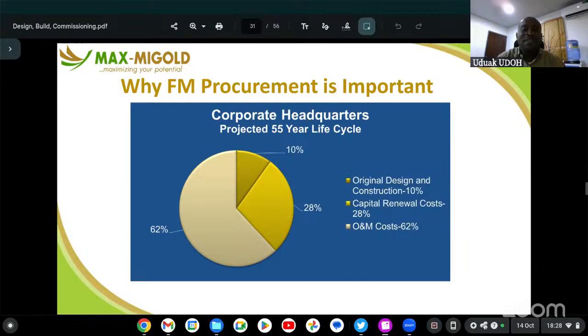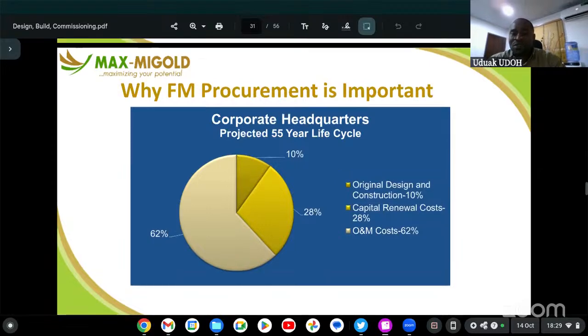And whether spares are available, because there are some things you get and there are no spares, so what will you do? If I'm getting a particular asset and purchasing it for like 20,000, for instance, and then weekly I'm maintaining that asset for 5,000, does it make sense? It does not make sense. That's just a scenario, because over time you see that you are even spending more on maintenance than the cost value. So we should always try to benchmark and balance our procurement whenever it comes to things we get on site, the asset purchase, and also whenever construction is happening.